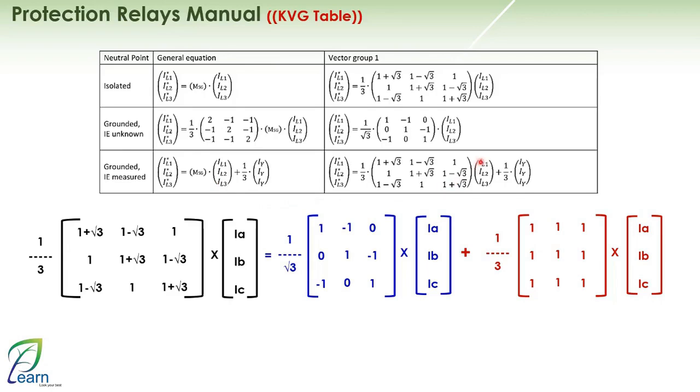It will take the fault current on the transformers and multiply it by the matrix, because it is supposed to subtract 1 over 3 of the neutral current. You see 1 over 3 of the current of what? Of the neutral current, which is IN. And of course, the IN subtracted will be at a 180-degree angle from the IN present here, and thus you have cancelled out IN with IN, as if you performed zero-sequence elimination, through what? By using the matrix you see in front of you. And with that, we have understood what this matrix means and how it was derived.